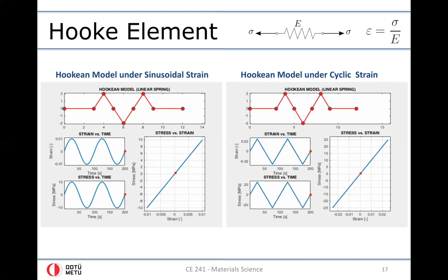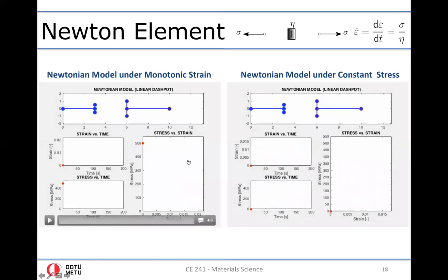Okay, so elasticity is the material response where we don't observe any rate dependency. We don't observe any delay, so the response is instantaneous. And we don't observe any dissipation. Loading and unloading curves are always on top of each other. In other words, the amount of work you do on the material is perfectly stored inside the material. It's like a perfect energy storage medium.